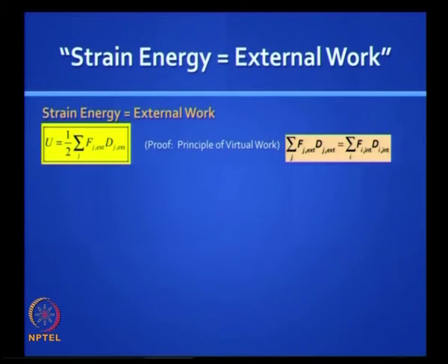Now one of the theorems which is sometimes very useful to apply is this concept called the external work done. When you load a system gradually from 0 to its maximum value, it will be equal to the total internal work. Okay. Remember, if it is a linear elastic system, the factor half will apply also to the external work. Okay. This is different from virtual work, this is real work,